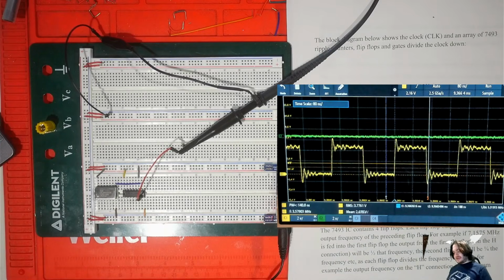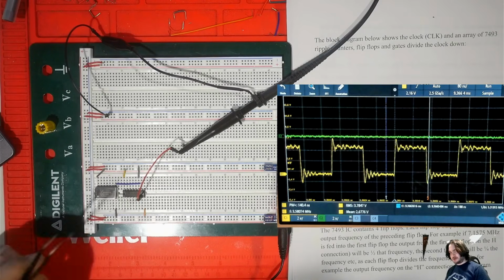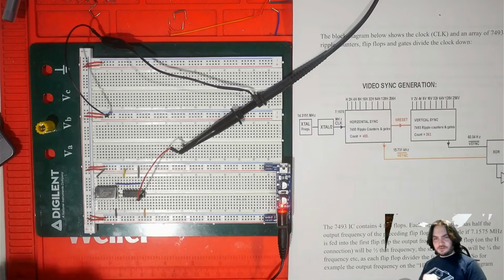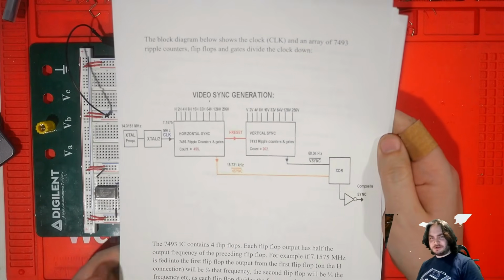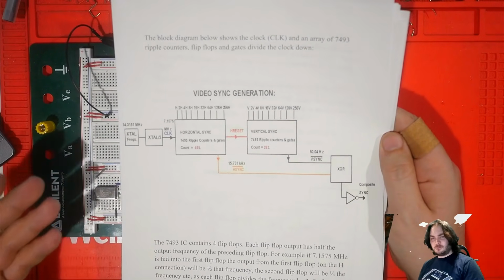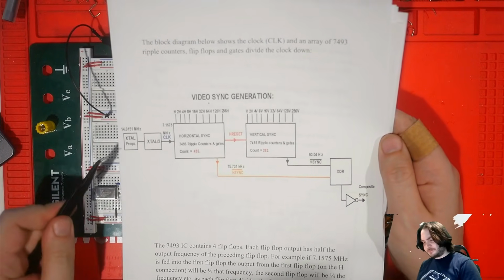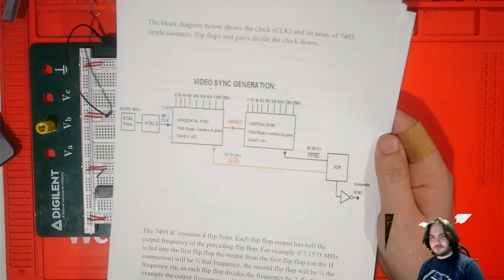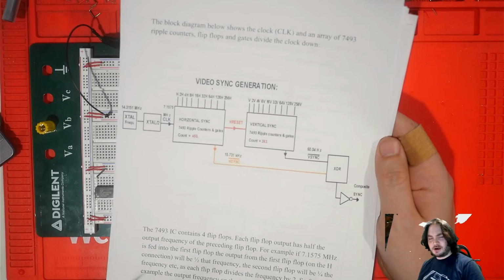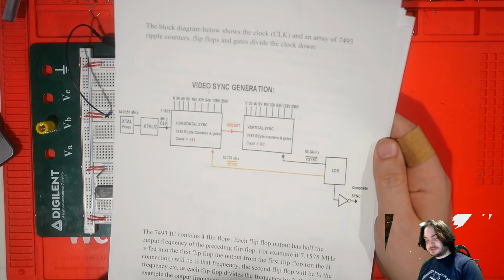We're dividing by 8, and as we called this 8x color burst, this is just the regular color burst frequency. The overall game plan here is that we want to generate a synchronization pulse that tells the TV when each frame and scan line starts. This is going to come from documents describing the circuit for original Atari Pong, and we're going to do a couple of things different.